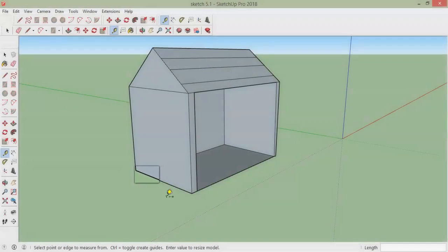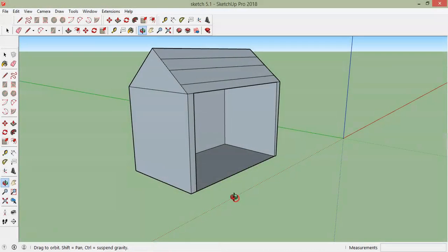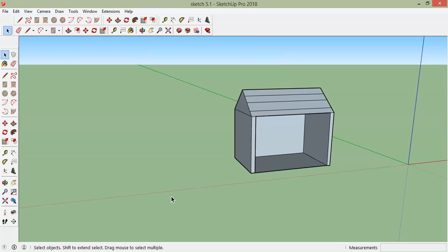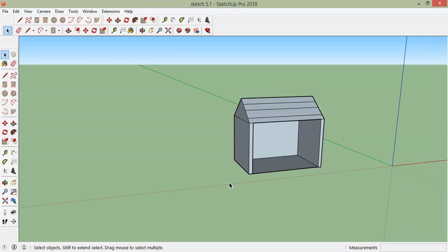Now we can say that the overall scale has been increased proportionally, but if you want to increase this sketch by 1 unit in each side, then you will have to type the final unit and extend to it without affecting the rest of the geometry. Let's do that together. First, undo by pressing Ctrl Z a couple of times. This figure is 5 by 3 units.